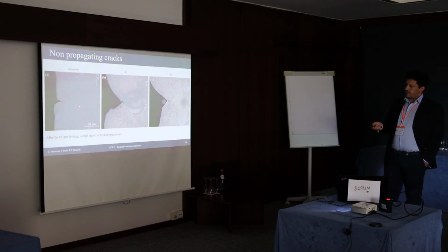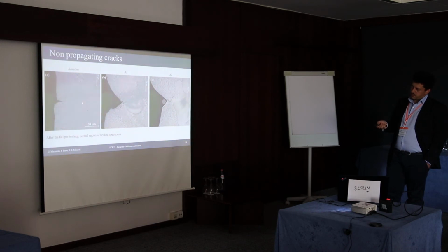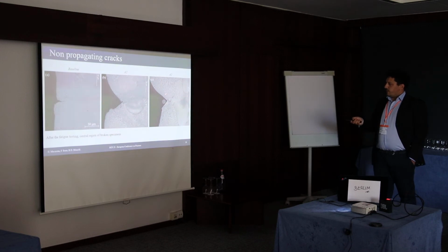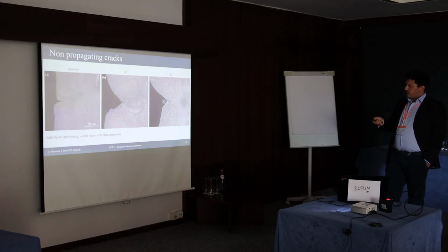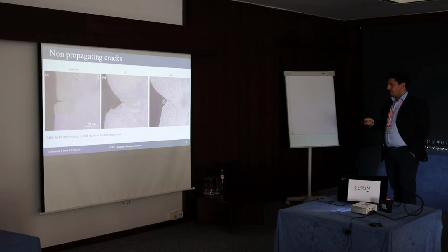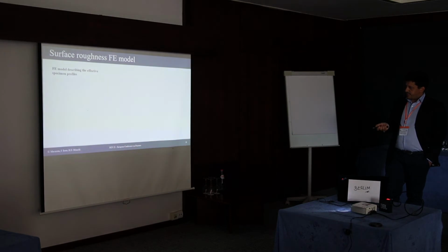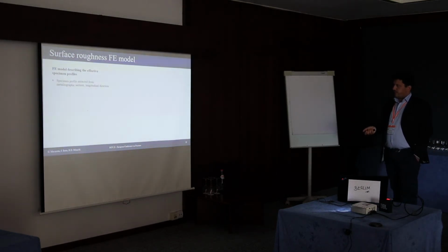We see that in the baseline case we have some small discontinuities in the roughness on the external profile of the specimen that are really sporadic. In the ATU case, we have a lot of these steep valleys, and at the root of the valleys we can observe these non-propagating cracks. They have a length of 20 to 30 microns, let's say. Based on this idea, we try to explain the fatigue behavior of this material.